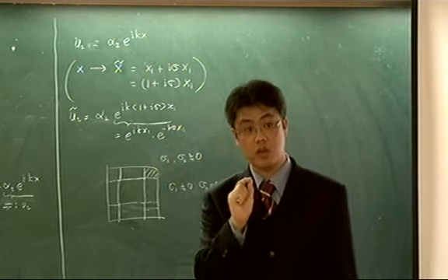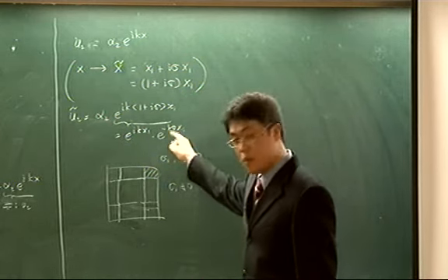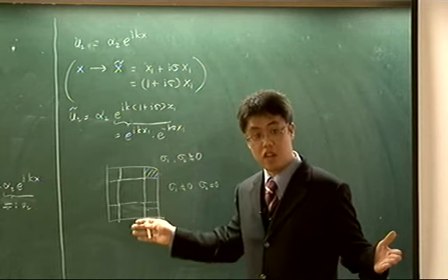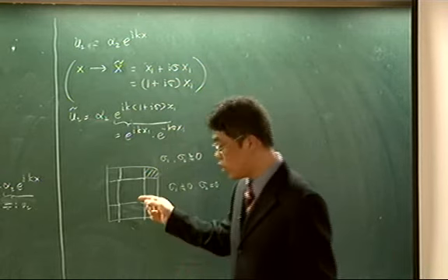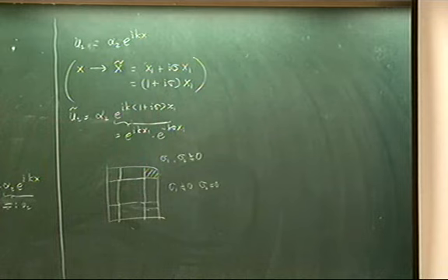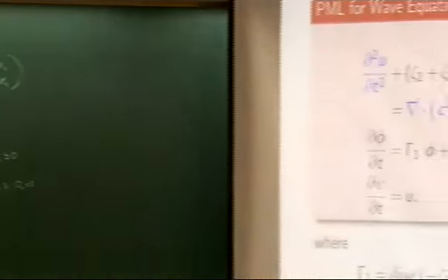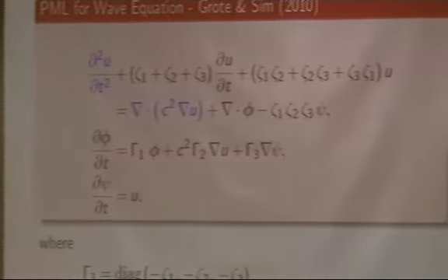So, right? You can control this with the damping parameters, or you can enlarge your computational domain for PML layers. Okay. So that is the new wave equation for PML. If you have this equation, you can calculate in unbounded domain all kinds of acoustic waves.